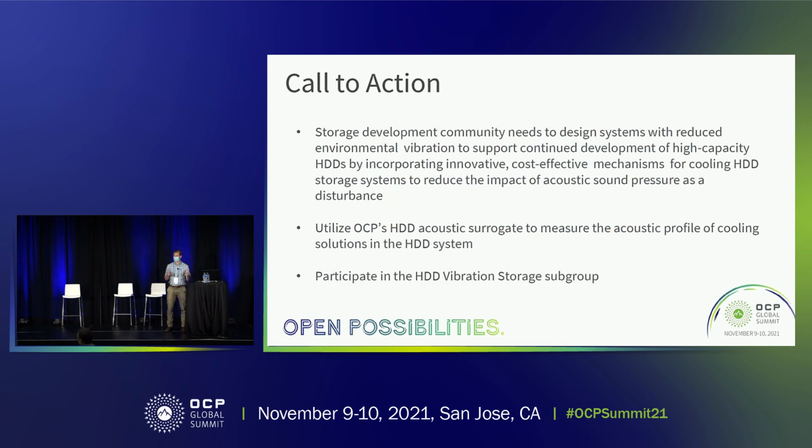So the call to action is, first of all, reminding us all that as we build these storage enclosures, we need to think about the acoustics to the drives, and vibration in general. How well the drives are mounted into the system, how well we damp the drive-to-drive interaction, but also what ways we can cool these drives in an enclosure to keep the acoustics down.